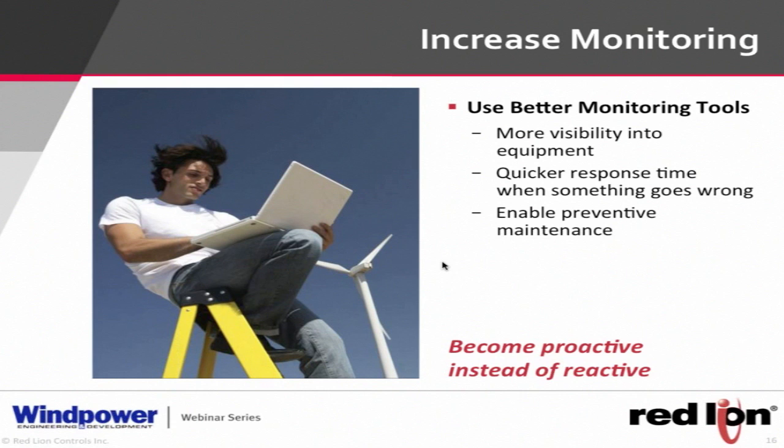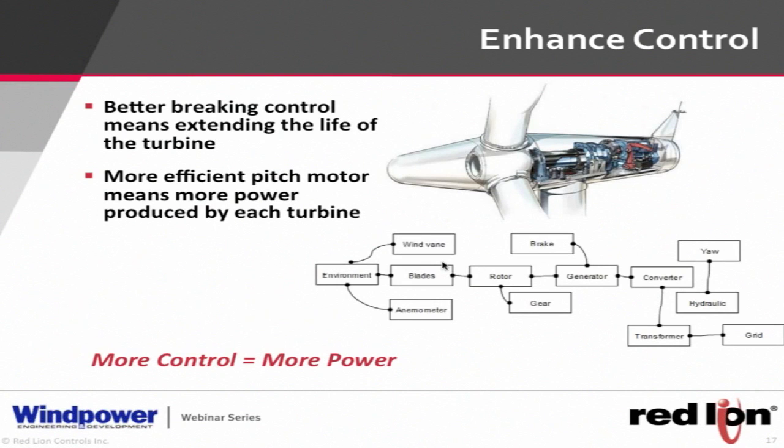So we can schedule work to be done at a certain time. We can look at what's going on, what the trend is, what the performance is of that particular turbine, and make sure we get somebody out there to do whatever maintenance needs to take place, instead of having to send somebody to the turbine just to guess. So it allows us to become proactive instead of reactive, which is what everybody likes. Looks better and works better.